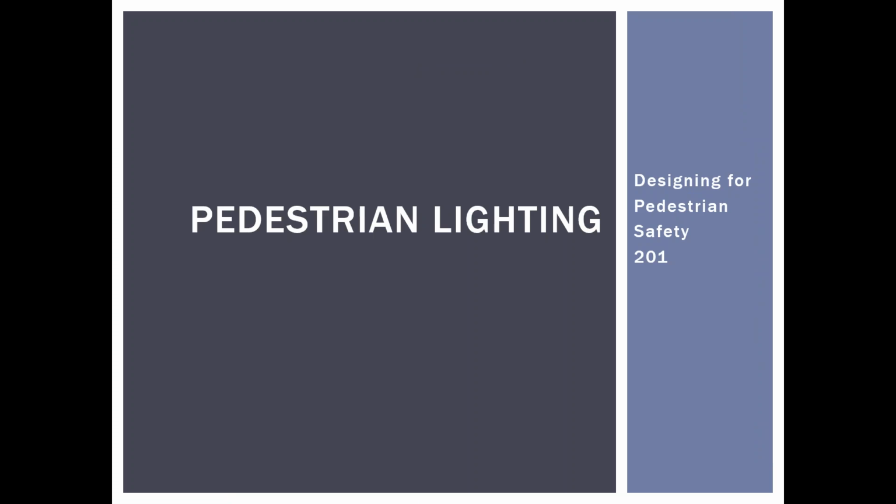Let me give you some of my background with respect to lighting and lighting experience. During my more than quarter century with Phoenix, I saw the city first purchase all of the street lighting equipment, the poles, the lights, the mast arms, from the two power companies that work in our region. I observed the conversion from originally, when I came in, everything was mercury vapor street lights, to high pressure sodium with 90-degree cutoffs to minimize light pollution to the observatories that we have in the state. Most notably Kitt Peak Observatory west of Tucson, and Lowell Observatory in Flagstaff, which is north of this area.